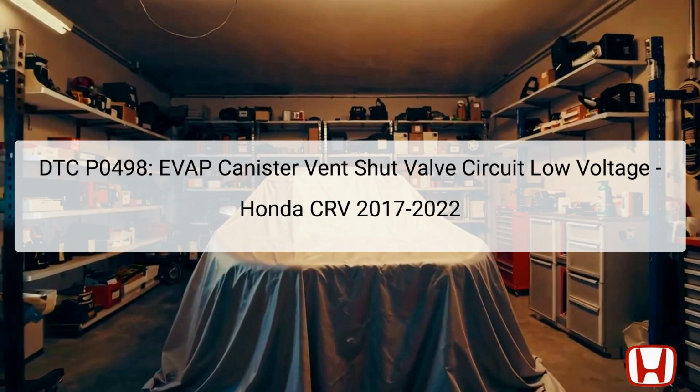The EVAP canister vent shut valve plays a critical role in this system by ensuring that the canister is sealed when necessary, preventing vapor loss during normal operation and maintaining optimal pressure in the fuel system. This valve is typically located near the EVAP canister, which is often positioned in the rear of the vehicle near the fuel tank.